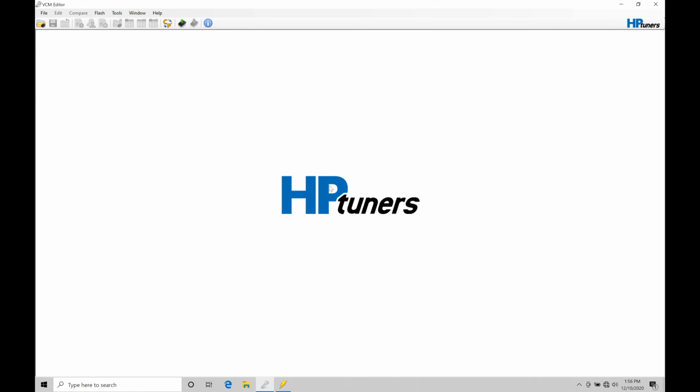Now the diagnostic section is going to be housing all kinds of things that we can turn on or off, functionalities or checksums within our PCM. So if we've deleted something from the car, let's say it's a sensor, we turned it off or we deleted it or bypassed it, and we want to make sure it doesn't throw a check engine light, we're able to do that in the diagnostics section.